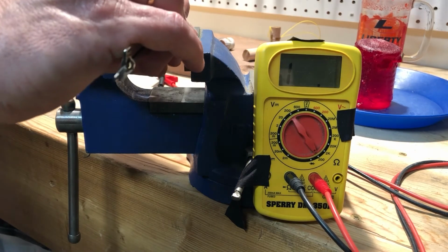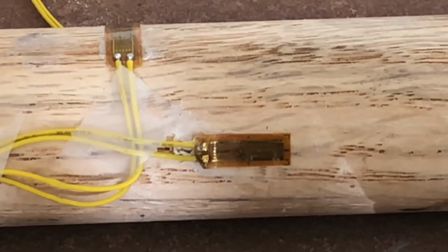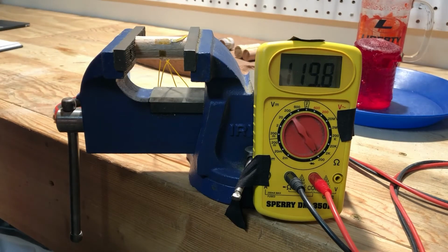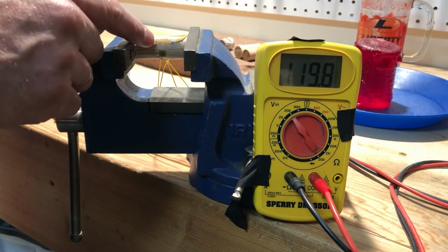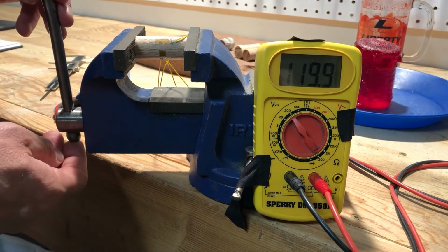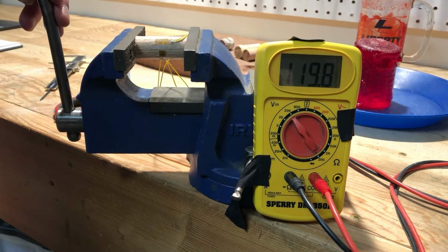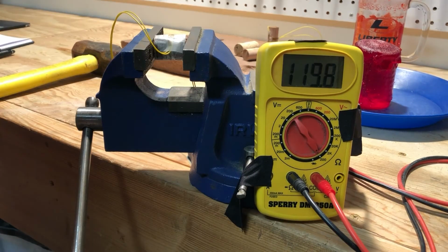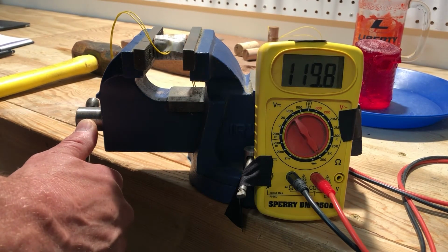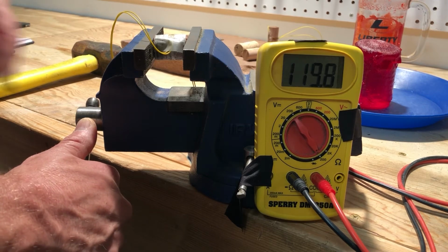For more sensitivity, I can also put strain gauges on these samples and measure the relative shortening of the sample's length and the increase in the sample's radius with these strain gauges. In oak, the sample bulges about 1/3 of the shortening. While for sandstone, I actually broke the sample, most likely due to not applying a uniform load. I can't really do this, I really need a lab for this.